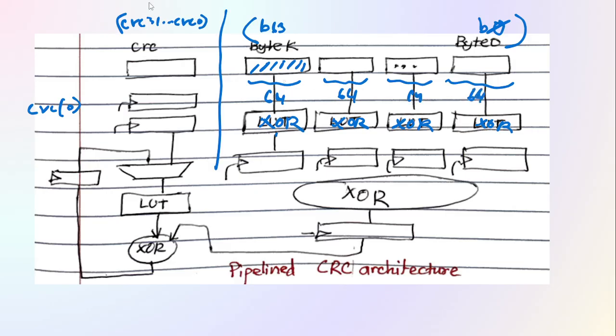I can write my function so that I XOR any 64-bit set, and then I flop it to improve my timing. Once I have 4 of those, I take the 4 bits and XOR one more time and flop it one more time, and there you go. I have very nice timing that might go to 800 megahertz.